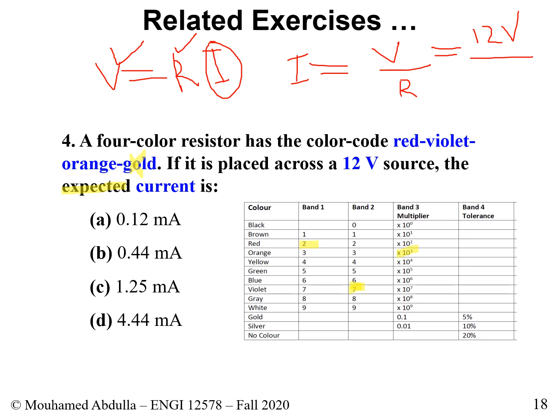Let's just write it. So this would be 27 times 10 to the 3, which is basically 27 kilo ohm. This is the resistance that we have. So here we simply put 27 kilo ohm, and let's see what we get. We could take the calculator. We do 12 divided by 27, and this should give us 0.44 milliamp, or the value that we have here.